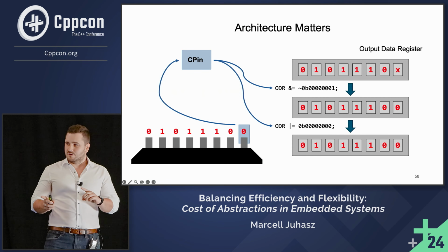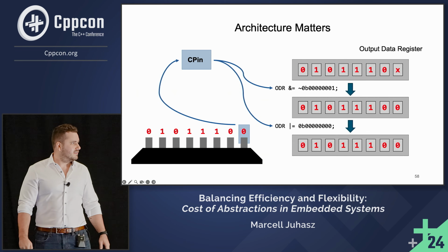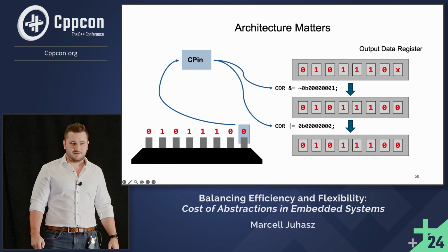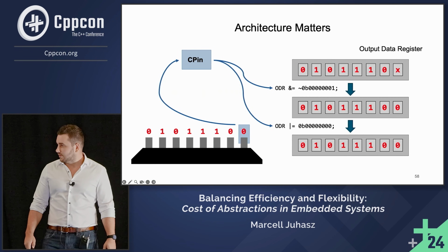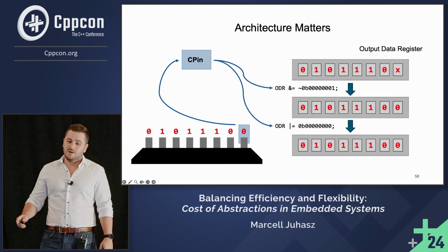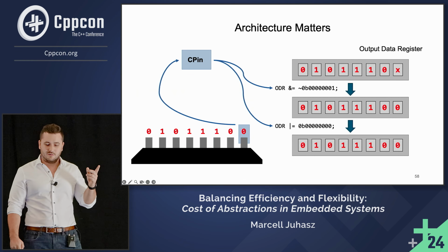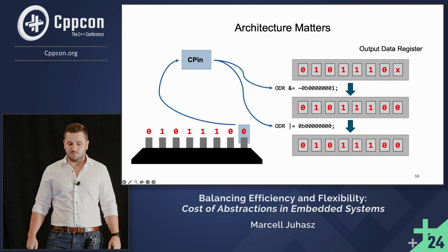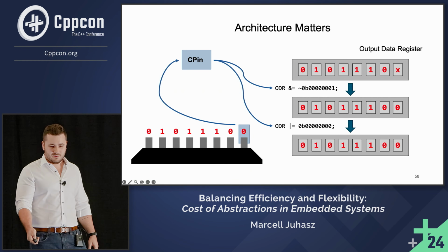And if we are thinking in terms of a wrapper around the hardware abstraction layer, then the case is even worse, because you have made 8 calls to the same hardware abstraction layer function. And this will introduce a lot of runtime overhead. Not to mention that between setting the first pin of the GPIO and setting the last pin of the GPIO, you have invalid values on your 7-segment display.